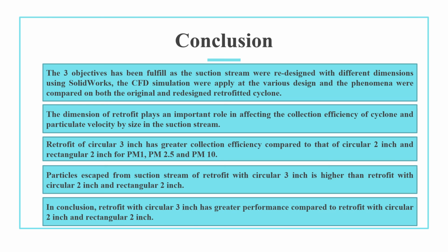The third objective has been fulfilled as the suction stream was redesigned with different dimensions using SolidWorks. The CFD simulation was applied to the various designs and the phenomena were compared on both the original and redesigned retrofitted cyclone. The dimension of retrofit plays an important role in affecting the collection efficiency of cyclone and particulate velocity by size in the suction stream.